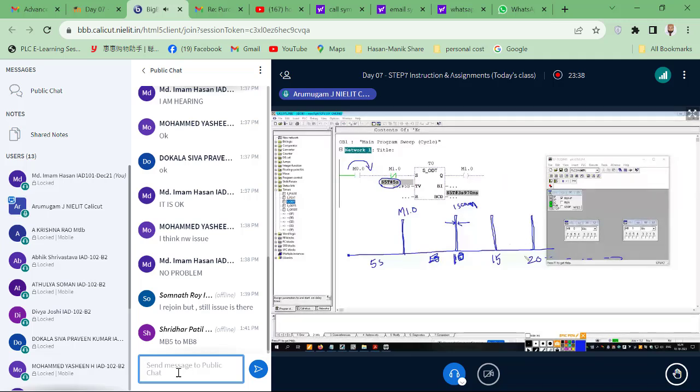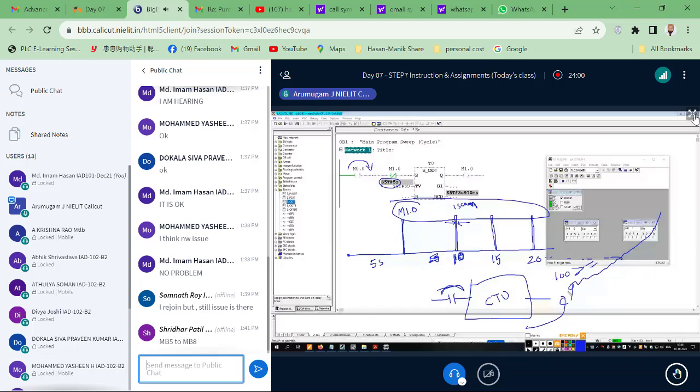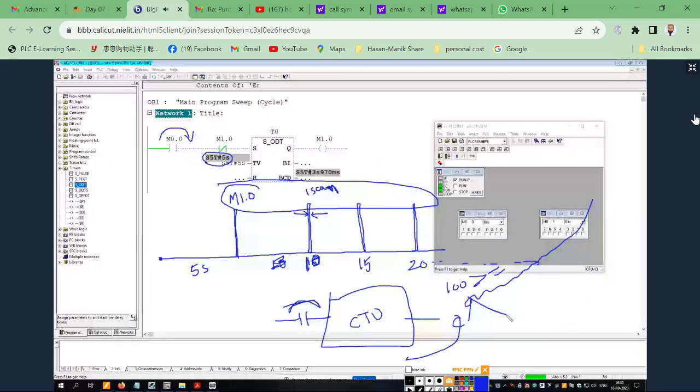Now this address we are giving to one count up, CTU. Then that switch we have to assign. Then this count up value increases 1, 2, 3, 4, 5 like that. If it reaches 100, you can use a greater than or equal to compare and a reset button. Then you can make a countdown. So that is the logic you have to try to identify.